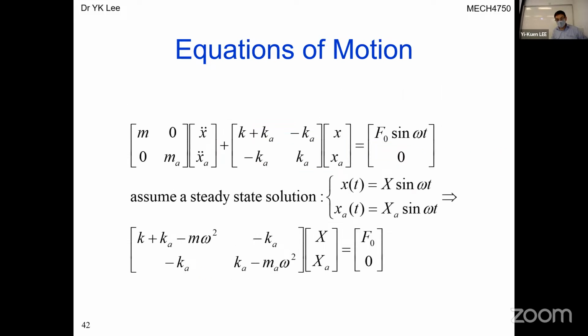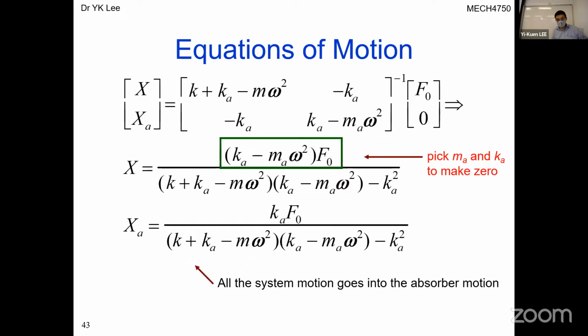We look at the frequency response function of this system. The original system has mass M1, and the vibration output relates to M1, while M2 is the absorber mass. We look at how the vibration amplitude is a function of frequency.